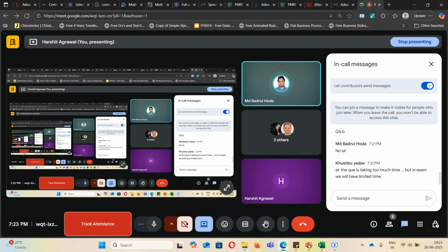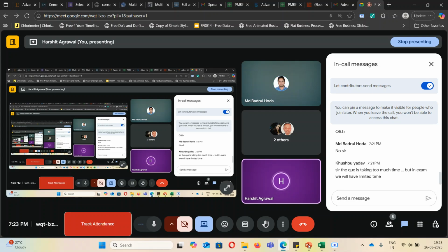Yes, after x, we can find Cc, the total compression in concrete. That is the approach. You also need to find the equivalent stress block elements. You know the strain in concrete, so you need to find alpha 1 and beta 1 also. When you know beta 1, alpha 1 and the value of x, you will get the net compression force.